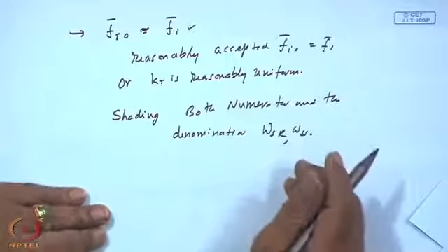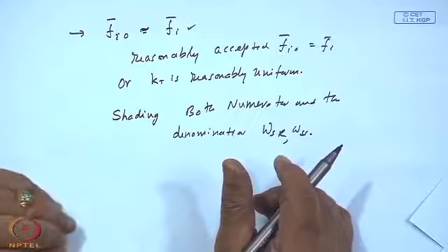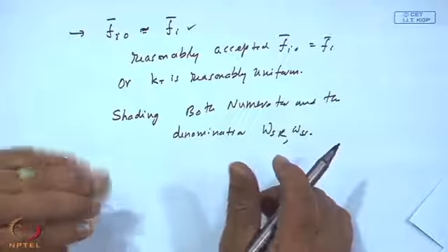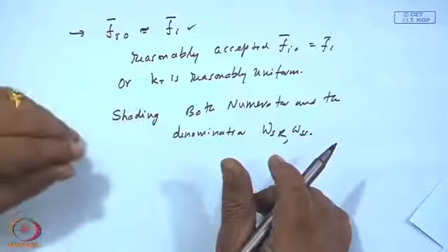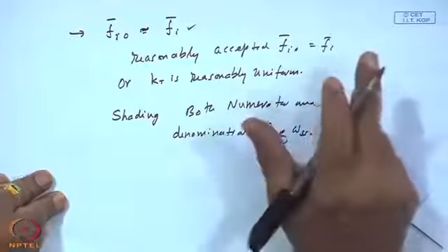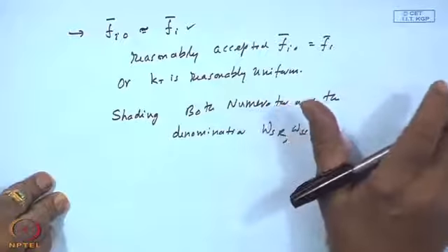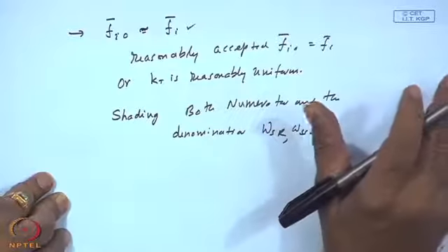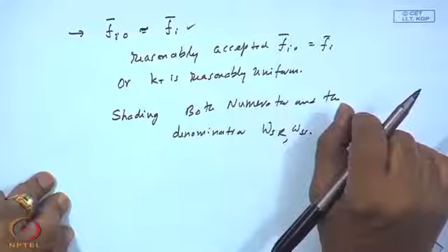Unlike in the case of our flat plate collector solar radiation received, where the integration is from omega SR to omega SS in the tilted radiation and 0 to omega S in the denominator, and that could make a difference in the time element of the numerator and the denominator. But as far as the shading factor is concerned, both of them are during the time period that they receive the radiation. If the radiation is not received by the solar collector, obviously there is no point in calculating the shading factor.